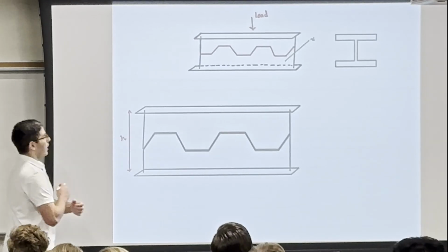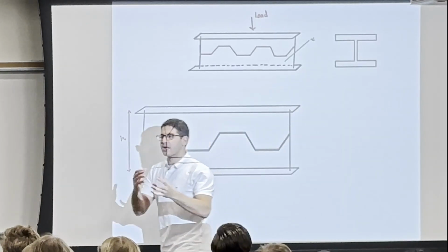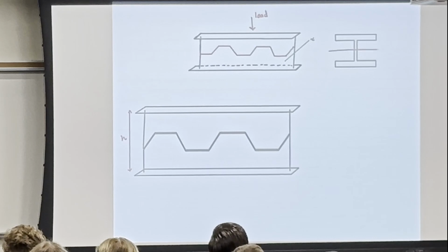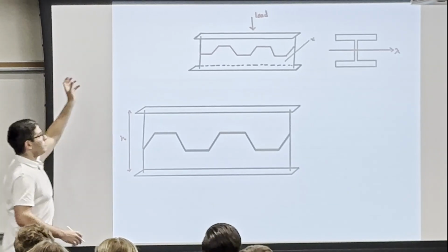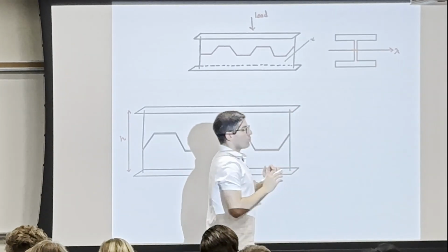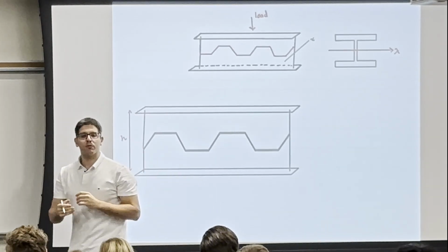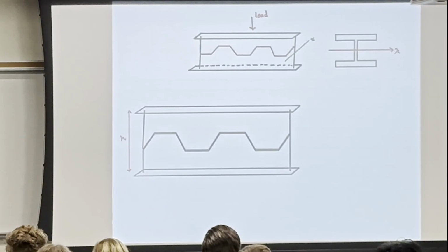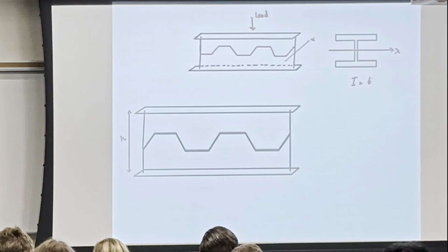So I do have a cross section like this. That's why you will always find, for example, the I section. And the I section here is basically what we are doing. We're throwing the area away from the centroid, to take two advantages. The first advantage is in the inertia, we have b h cubed over 12. So I have the height cubed.